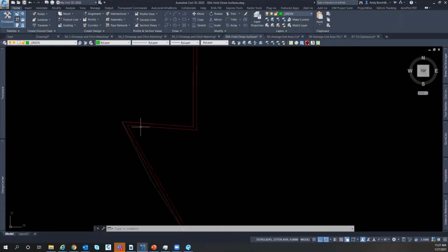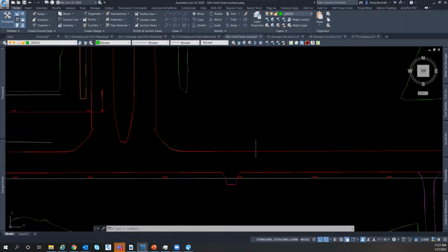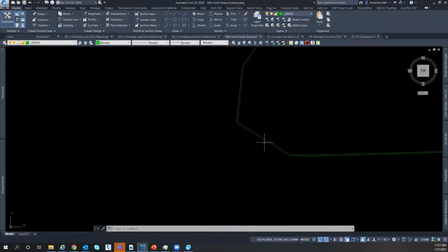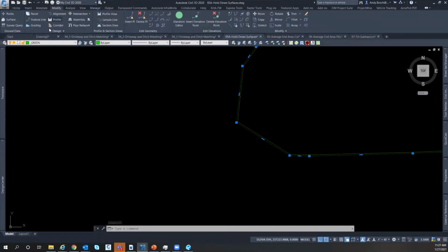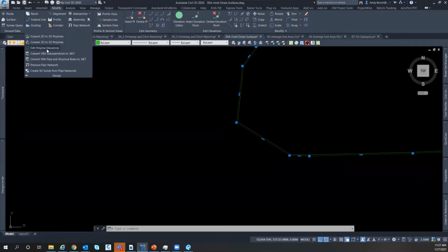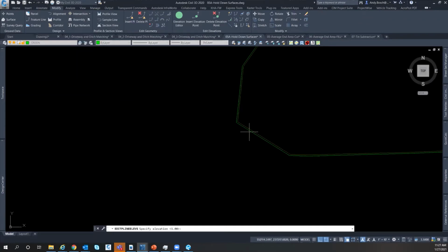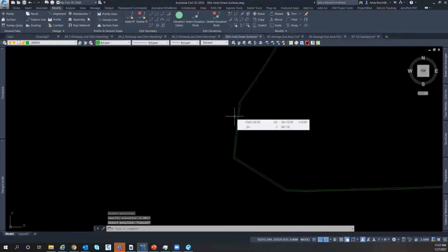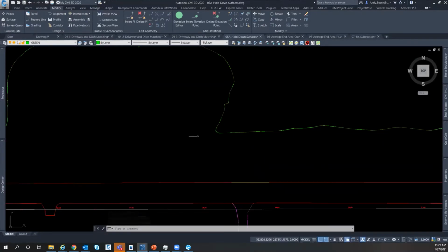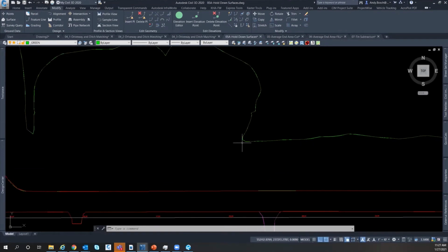As you go around, you create all these different areas. Once I get these all created, and these are nothing more than polylines, I'll go into my modify and design and do edit polyline elevation. Right now this is set to 1 foot for this polyline, and that's good enough for me. That's the elevation that I want, and that's what my given hold down is going to be for my green space. I want to take out 1 foot of topsoil in all the green spaces.